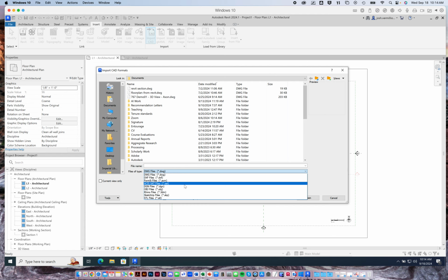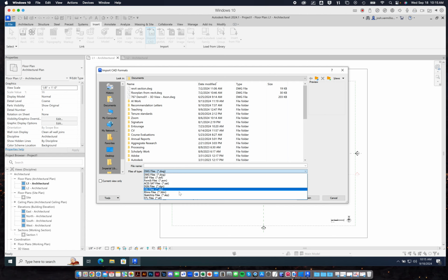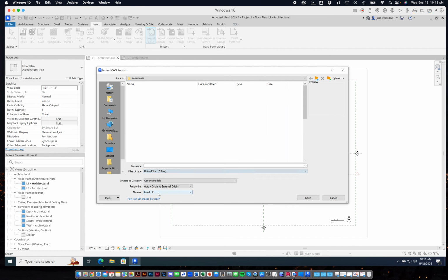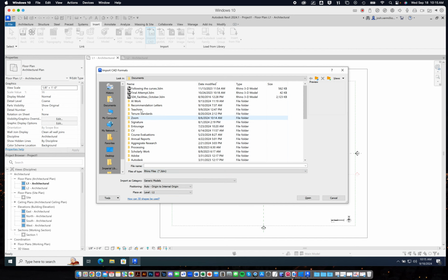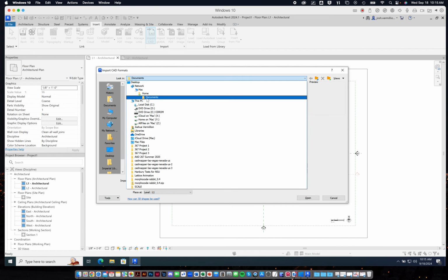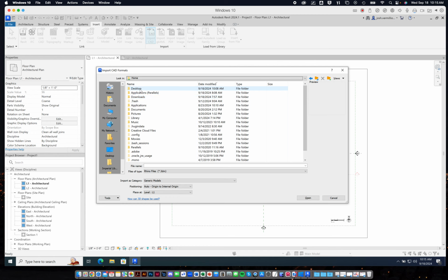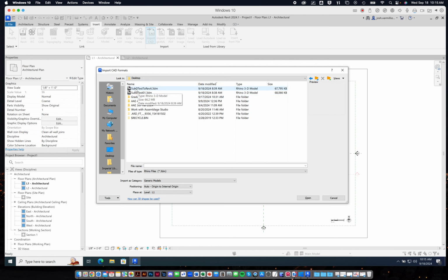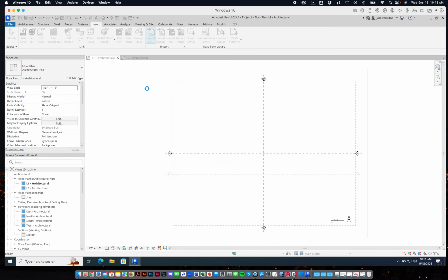You guys know all your file types, right? Some of them, probably. Yeah. All right. So we all know 3DM, that's Rhino. And look at that. I can go now to where I saved my new Rhino file. I called it subd test to Revit, right? Sort of labeling it as this is the thing you bring into Revit. And let's just go ahead and import that in.